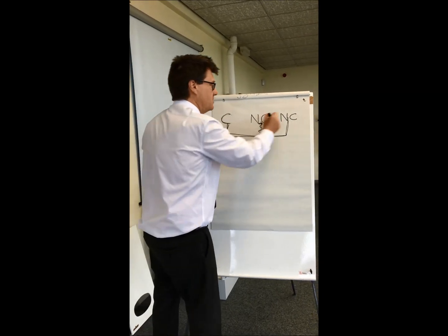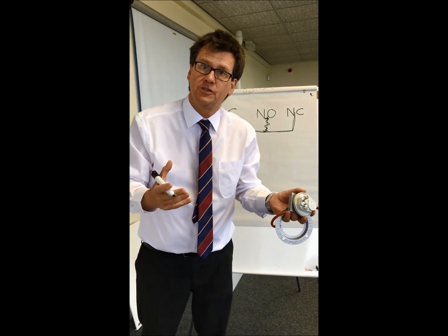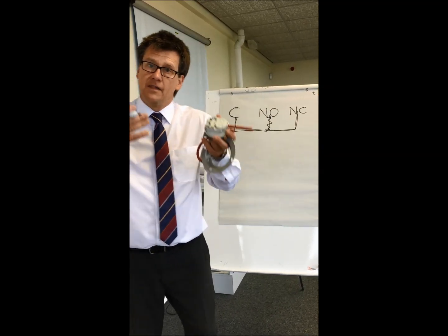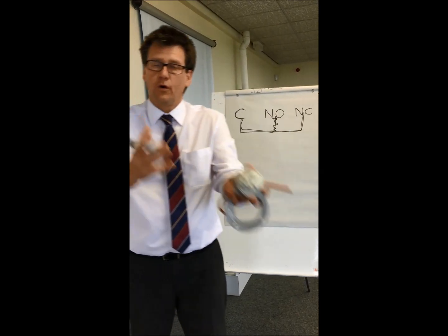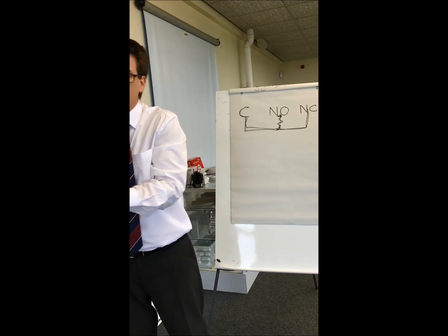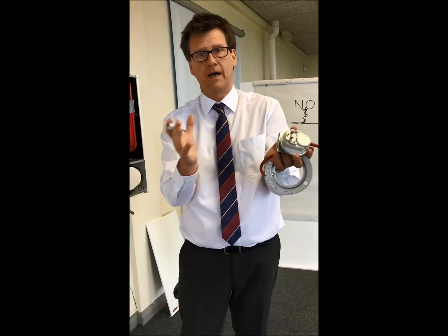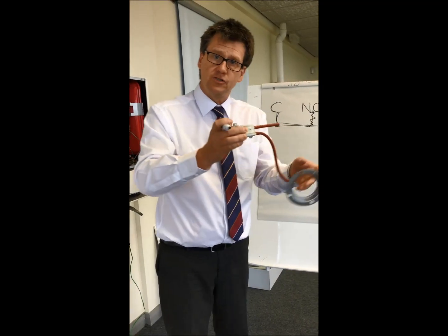Once it sees that there's continuity between common and normally closed, it knows that the air pressure switch is there, doesn't it? And when it knows that, it allows the fan to energise. So that is the thing that will throw you off track where you would buy a PCB. It's not the PCB. Just remember what I'm saying to you. PCBs are bulletproof, guys. All manufacturers.